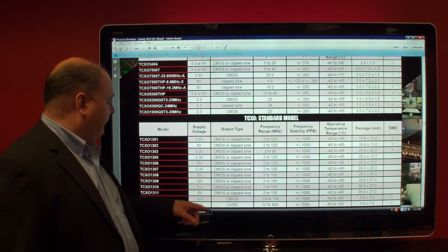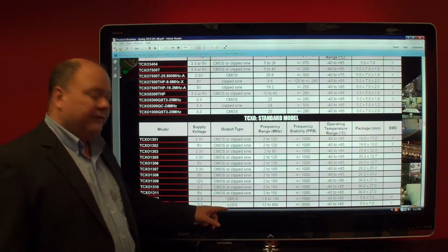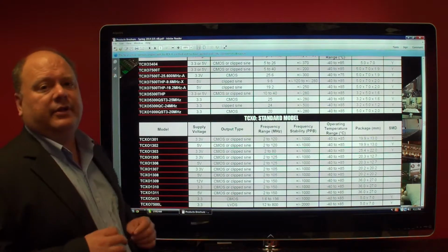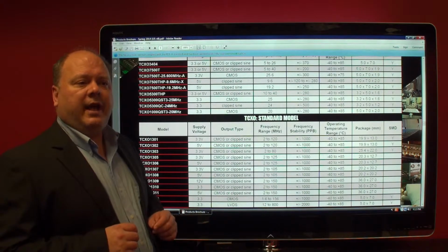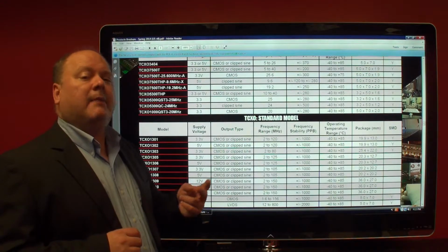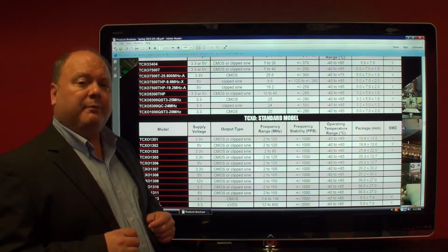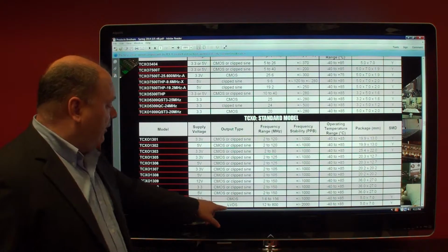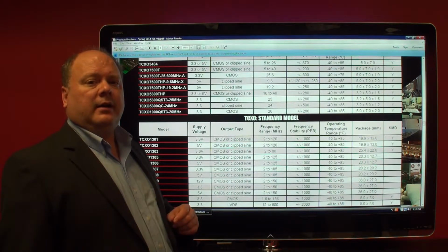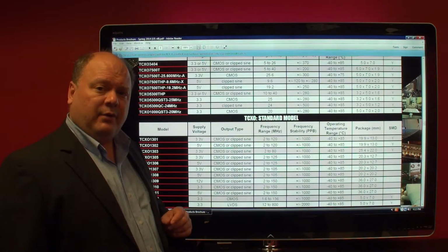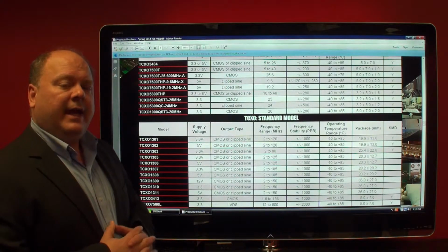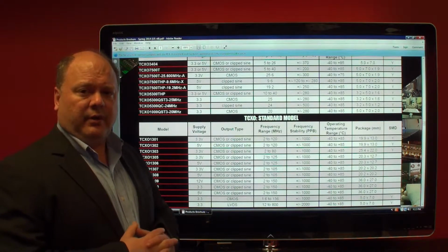We even have a 5 by 7 millimeter LVDS output, differential outputs. For TCXOs with differential outputs, you have two different RF outputs, a regular output and a complementary output. Same with PECL and LVDS. So we can offer LVDS TCXOs. They're not as popular as the CMOS or clipped sine wave type. Those are your most common outputs, clipped sine wave and regular HCMOS square wave.